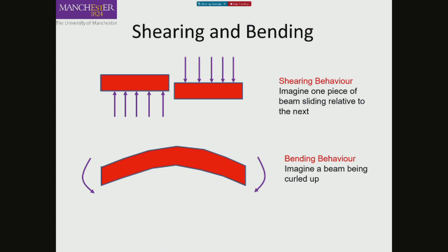No, the sequence is that imagine you have got a flat beam on a support. You put a load onto that beam, and that load will go to the support. Whatever you put on, that's the whole purpose: take the loads. Imagine this is a bridge. You are standing in the middle of the bridge. Your load must go to either of these two ends, right? Now, the way the load moves to the end side, it creates so-called bending stresses and shear stress within the beam.